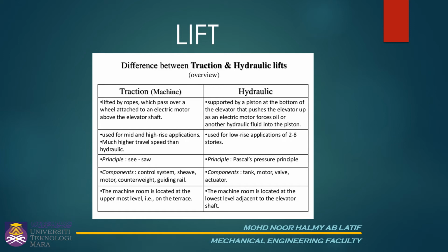While for hydraulic, the lift is supported by a piston at the bottom of the elevator that pushes the elevator up as an electric motor forces oil or another hydraulic fluid into the piston. It is used for low-rise application of 2 to 8 stories. Components: tanks, motor, valve, actuator. The machine room is located at the lowest level adjacent to the elevator shaft.